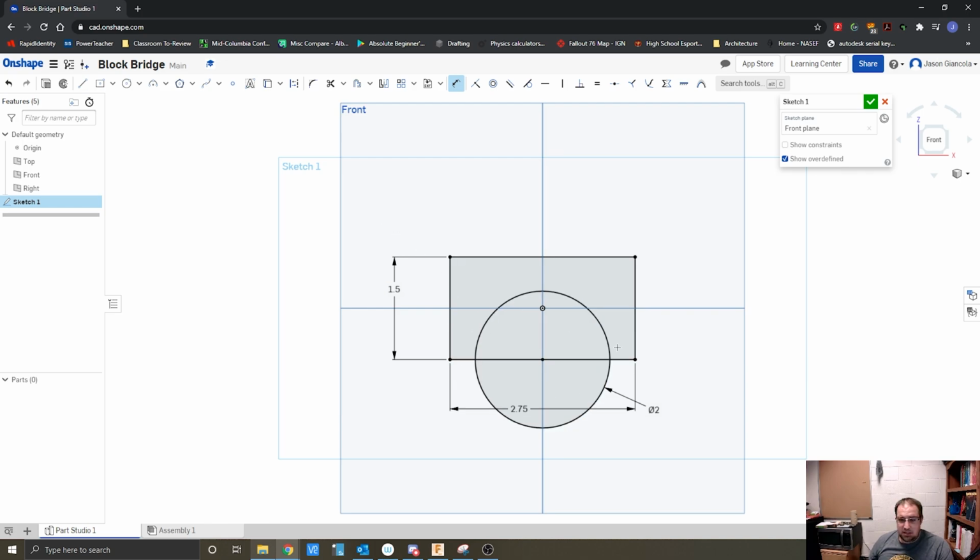Now that's currently sitting in the midpoint of this line, but we're going to go through and cut or trim away some of this profile stuff. Okay. Now you can see that our line disappeared down there, our dimension, which means that these lines right here need to be redefined. We can go and do that. Okay. By selecting that top line and placing it. There's our bridge, and now we just need to extrude it.